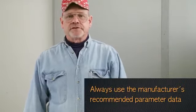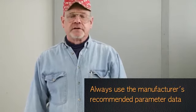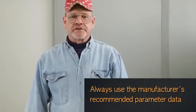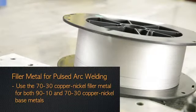We'll be using a particular pulsed gas metal arc power source and wire feeder. It's important to note that there are many manufacturers of such equipment. For the equipment we're using the parameter data that we obtain from the manufacturer. In every case, check with the manufacturer of your equipment to get the best parameter sets for welding the copper-nickel alloys. In this segment, we'll do pulsed gas metal arc welding with 70-30 copper-nickel welding wire.